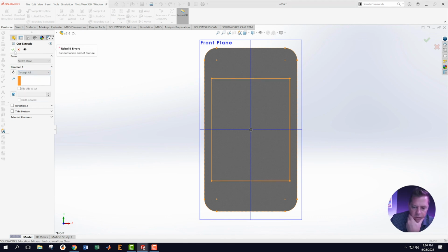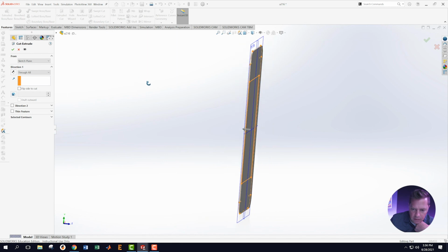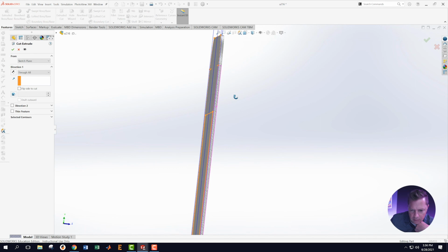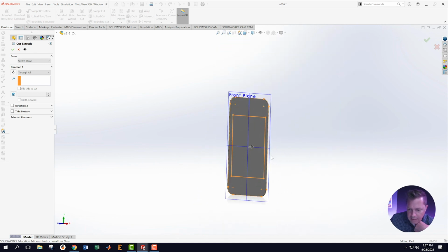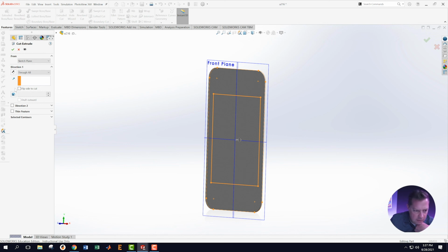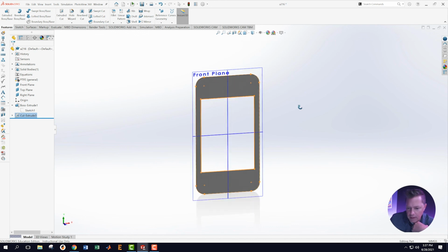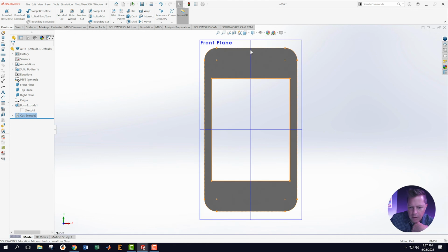But I have some sort of other problem because of the following. Okay, look what it's trying to do. It's trying to cut in a direction where there's no material. Okay. Remember before when I said I wasn't sure if we had created the gasket in the right direction? The way to solve this is to hit this button. And now we have a preview showing up, which is excellent, first of all. And that means we now have this thing just the way we want it.